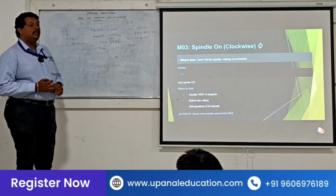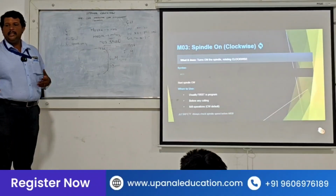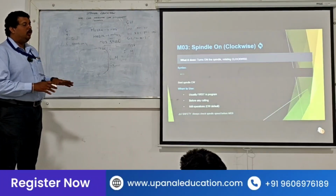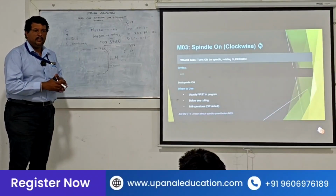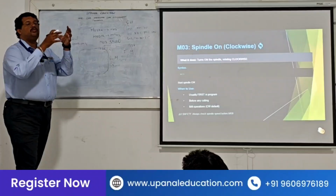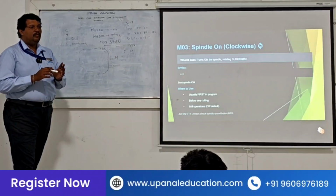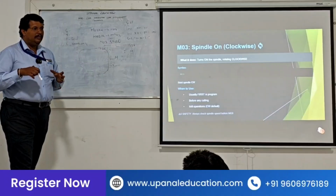See, for example, what we do? Sometimes your machine is idle for so long, or we have changed the spindle. Say we have a 12,000 RPM spindle, but we need higher speed work, so we take a new spindle and set 40,000 RPM. How do we start? First we start from 1,000 RPM. We run for 20 minutes or so at 1,000 RPM. Then we change it.